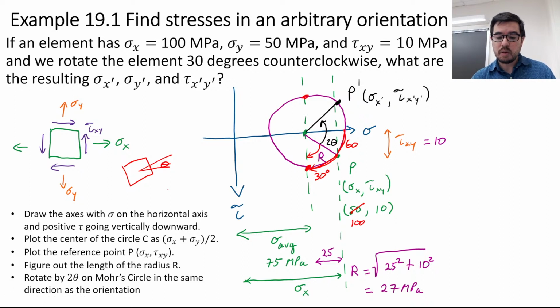And so a state of maximum in-plane shear stress can also be said to be minus 15. Half of 2 theta is 30 or minus 30 degrees, and so theta S can also be minus 15 degrees.